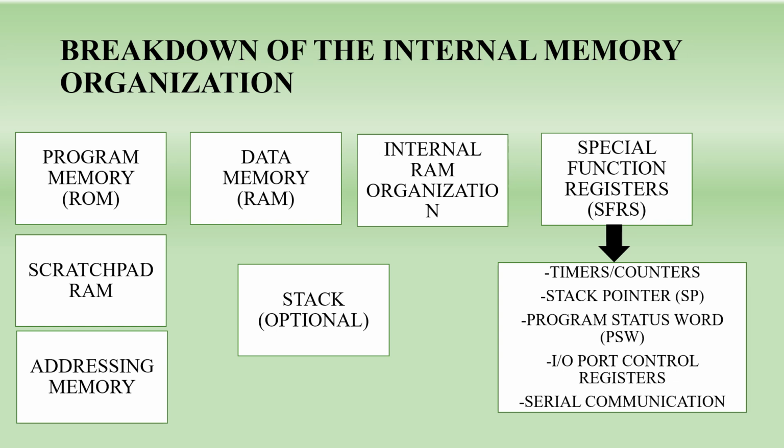So here it is going to hold the flags, that is overflow flag, zero flag or carry flag, indicating some outcome of the operation. If you do addition and you have a carry, it is going to give you the carry flag, telling that it is the outcome of the operation. Then input output port control register. This is managing the data direction, that is whether it should be an input pin or an output pin. For such purposes, control registers are used.